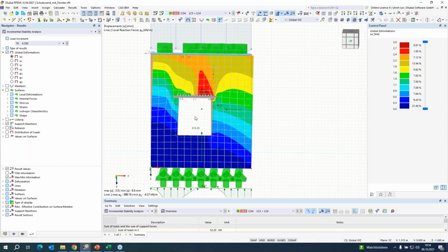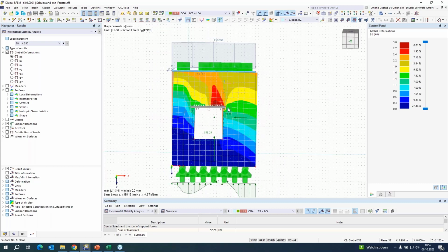So it is not possible to create such an opening, such a window in this existing wall, because then the wall is overloaded. But when it's needed to create an opening, what could we do? Maybe we would have the possibility to create something like a frame inside of the wall, inside of the window. Maybe then it would be possible, and it is very easy to compute it.